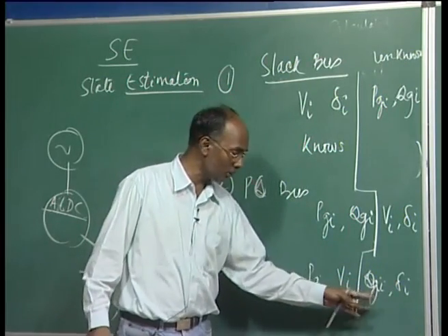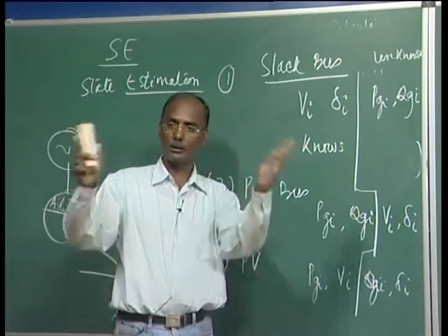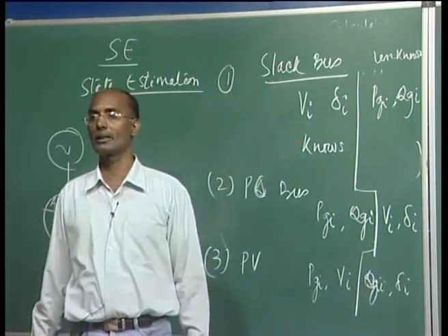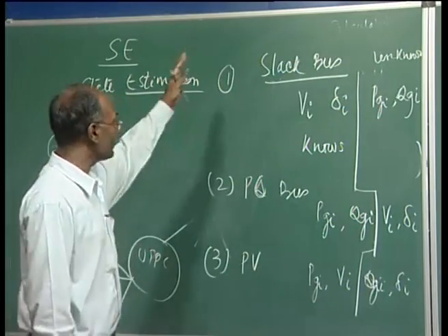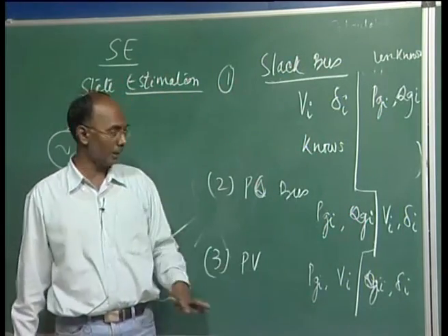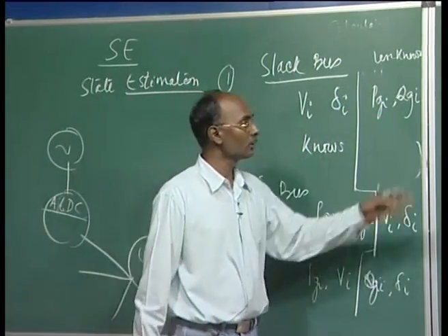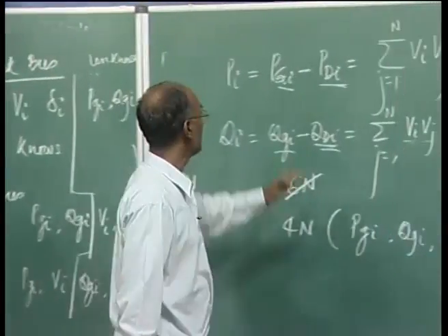So, the voltage here, Q is basically the Vi, and the network information will set your reactive power generation at that bus. So, these basically are the 3 buses classified. Now, we fix two known quantities, so we can solve this power flow equation.